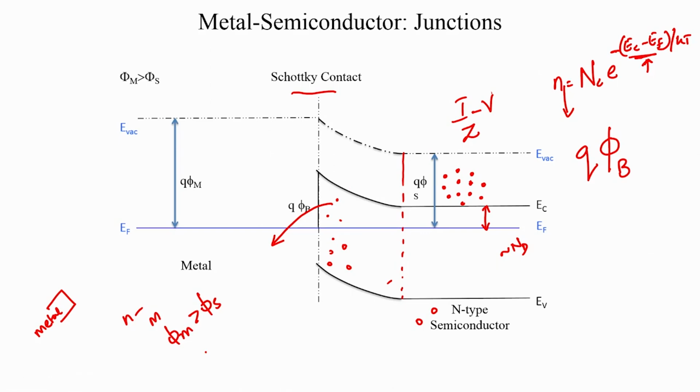Now, void is a very powerful word. It does not mean that there are absolutely no free carriers. What it means is that the free carrier count is much smaller compared to the static charges present in this region. So, what are the static charges? Since it is an n-type semiconductor, we had initially doped the semiconductor with a lot of donor dopants. At 300 Kelvin the semiconductor is extrinsic and all the dopants are ionized, and what we have is fixed positive charges in this n-type semiconductor. These charges cannot move, they are a part of the lattice, and these ionized donors gave up an electron which had become a part of your free carrier concentration. How many of these ionized charges are there? We have Nd per unit volume.